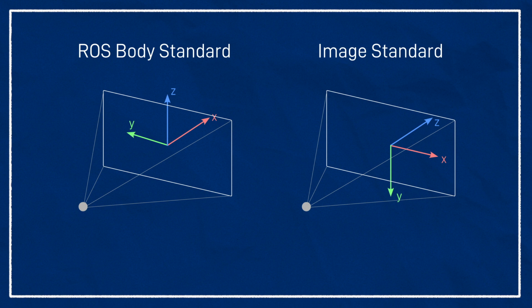So whenever we're creating URDF with links, or we're creating a transform tree, that sort of thing, we always have two different frames. We usually call the one that's in the ROS coordinate system the camera link, or something like that. And then the one that's going to be in the vision frame, which is exactly the same as this frame, but just rotated differently, is the same name, but with _optical.